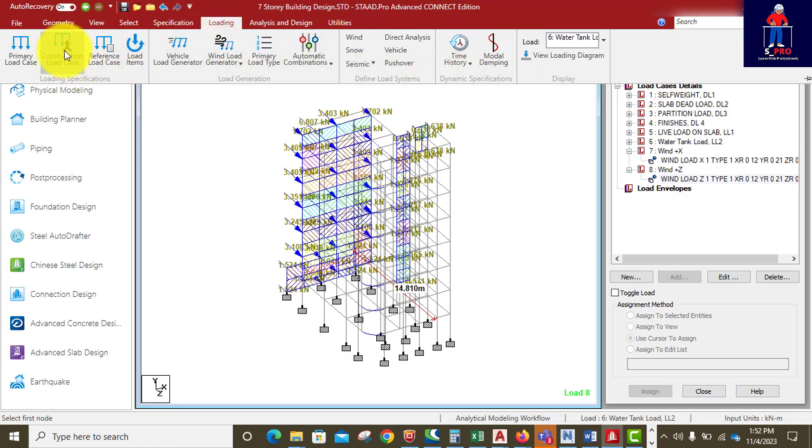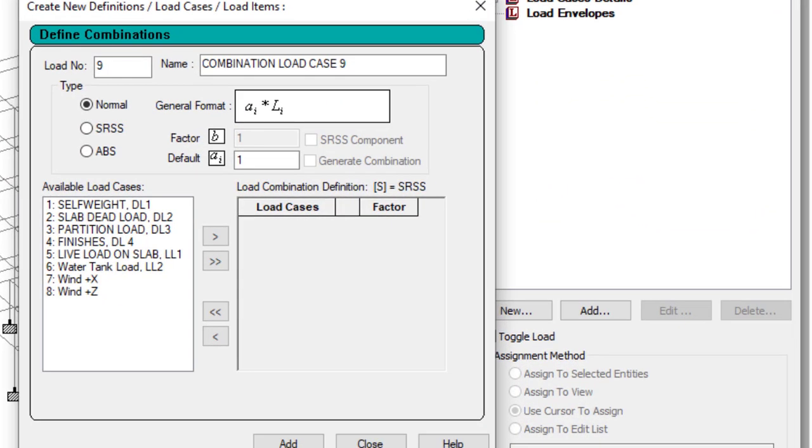Okay, your load combination you have to do in accordance with the particular code and standard they are using. So this combination I'm going to do here is going to be based on Eurocode standards. If you are doing American code, the only difference is the load factors. In Eurocode, when you are considering ultimate limit states, the dead load is multiplied by 1.35, while the live load is 1.5.